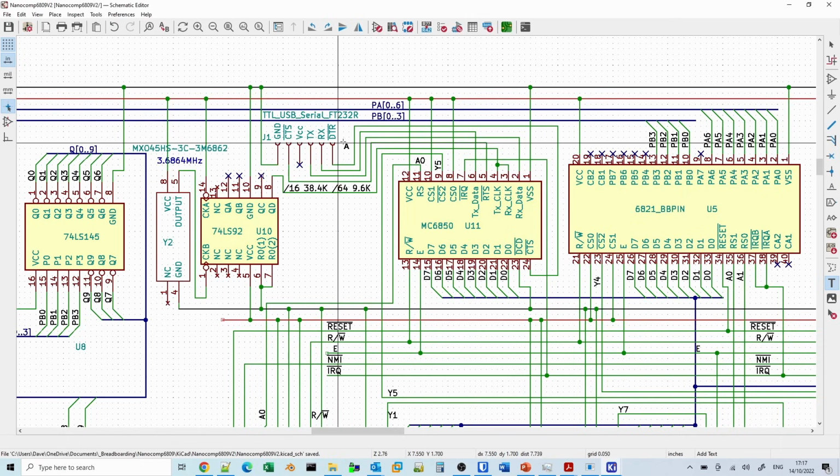So we do need to leave at least 6 lines or so between these two chips so that we can plug that in and hook all the wires in. Okay, so what we're going to do now is to go to the breadboard, put some chip labels on our chips and start laying things out.